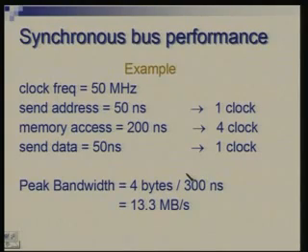So now the entire sequence is very clear. In 1 cycle you send the address, then for 4 cycles you do nothing, wait, and then have another cycle to transfer the data. So on the whole you require 6 cycles or 300 nanoseconds for transferring one word. Let us assume that the bus width was 4 bytes.